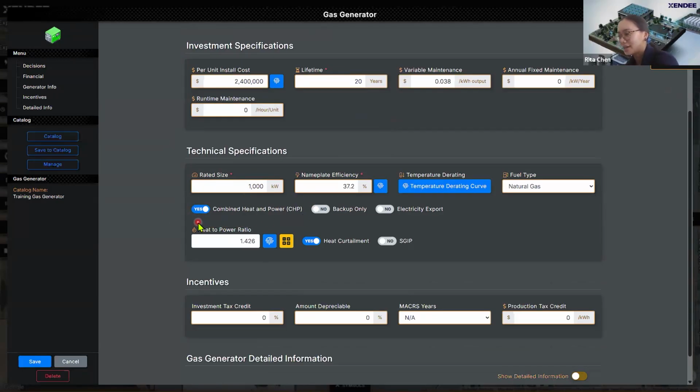So essentially, I'm going to utilize this as a cogeneration unit where it can generate electricity, but you can also utilize the waste heat, either to meet your heating demand if you have one, or we can use this in conjunction with an absorption chiller and use that waste heat for cooling. So that's what I'm going to do in our little example here, is actually use this in conjunction with the absorption chiller. And this is going to be a really powerful driver for saving not only costs, but also on carbon emissions.